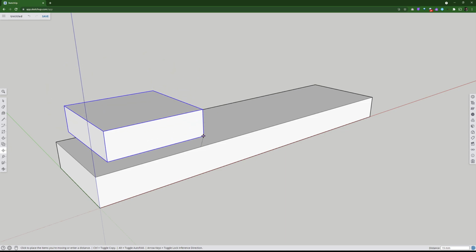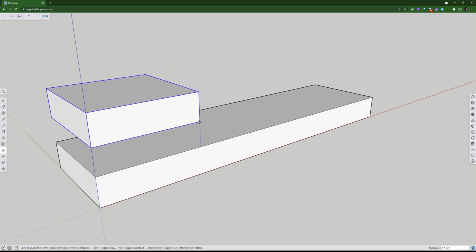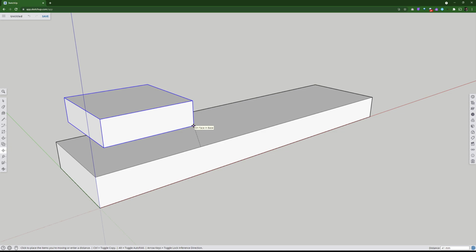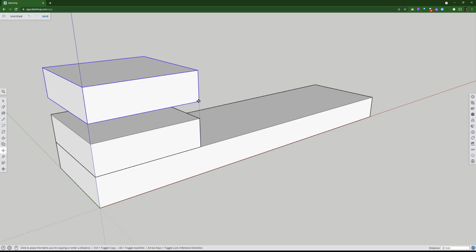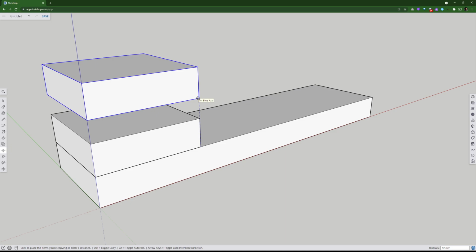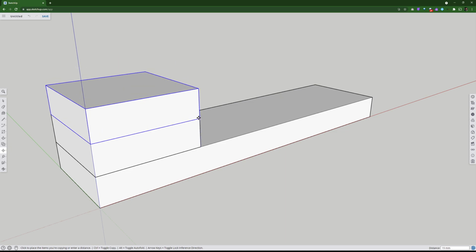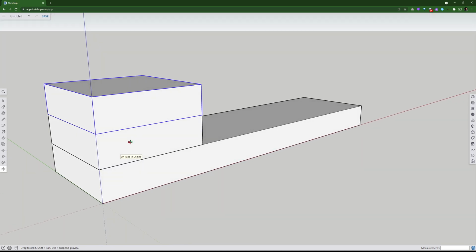Okay, so you can see where I'm moving 90 degrees along the Z. I'm going to do a very handy little technique. I'm going to press Control. Control will make me a perfect duplicate, the exact same part copied again. Because I selected it from that corner, I can snap it to the next corner. And I've got my engine.